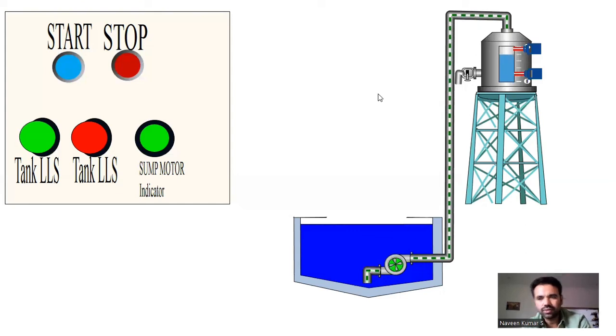See, it is going to turn off the motor. And we have programmed this: if there is data from the sensor, it has to blink. Now you see when I open the tap by pressing the left button, the water drains out. And the motor will be turned on automatically when the water goes below 200 liters.